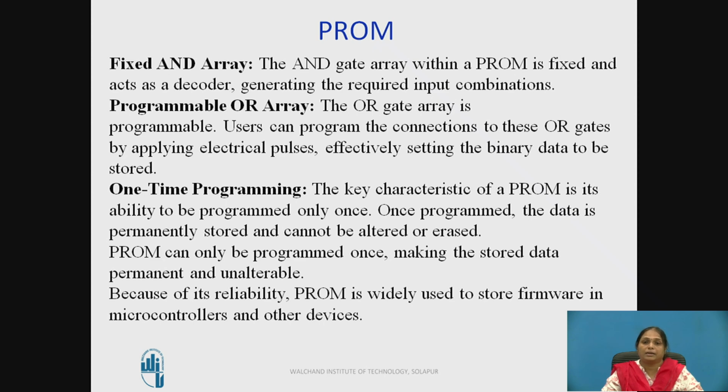PROM is programmable read only memory. The AND gate array within the PROM is fixed and acts as a decoder, generating the required input combinations. The OR gate array is programmable here. Users can program the connections to these OR gates by applying electrical pulses, effectively setting the binary data to be stored. It is one-time programming.